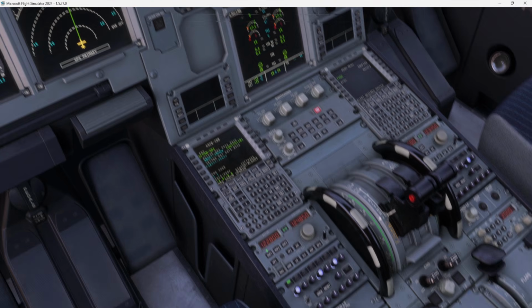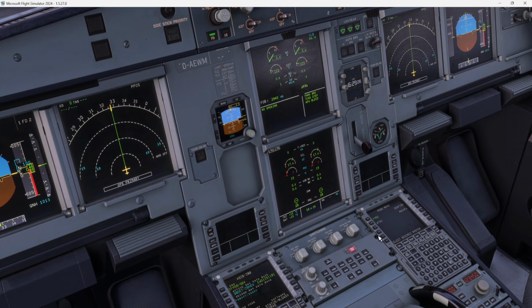Once we have engine 2 running, what we need to check, the most important thing, I forgot also to talk about EGT. EGT, guys, is the exhaust gas temperature. So we measure the temperature of the exhausted gas, and it should be under, I think, 725 or 720, if I'm not mistaken. I'm going to check it after the video and tell you if it's correct or not. If I don't say anything, it means it is correct.